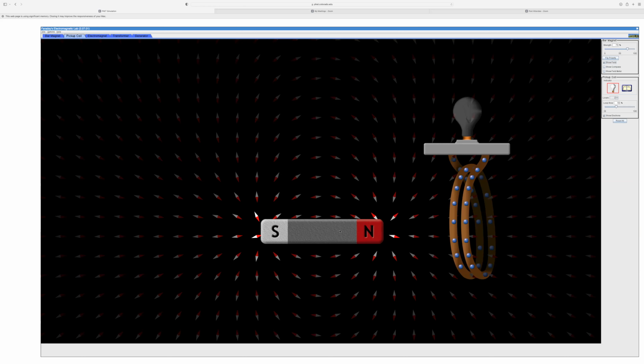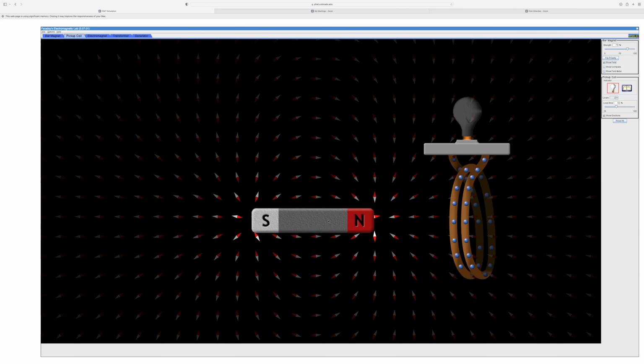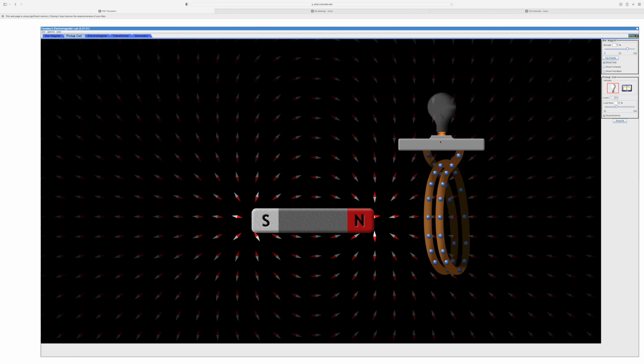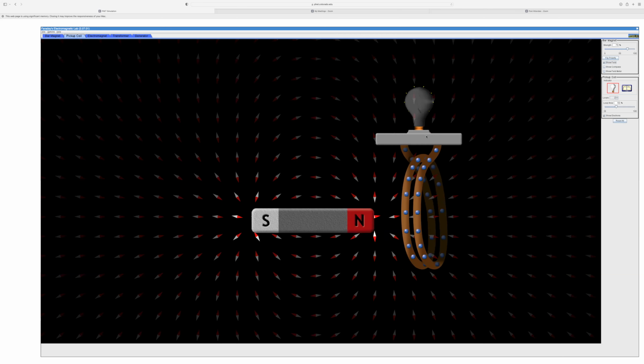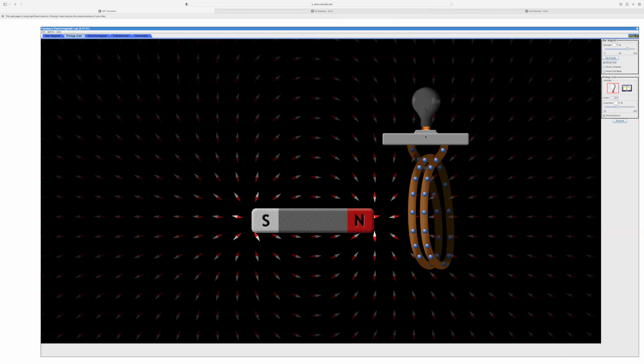Okay. Now comes an important question. Is it necessary that I always need to move the magnet towards the coil, or can I do the vice versa as well? Yes, I can do that because it will still work. Because irrespective of whether you move the coil towards the magnet or magnet towards the coil, one common factor is you are changing the magnetic flux associated with the coil, right? So when the magnetic flux is changed with respect to time, using whatever means you want, you can generate EMF. So this is the basic principle on which generators are designed.